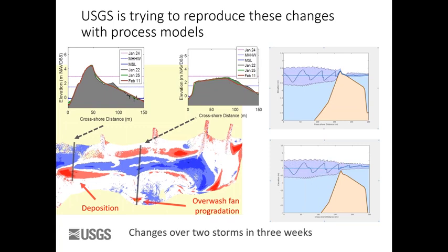This is SWASH. So SWASH is a Boussinesque-like wave-by-wave modeling system, and it's got multiple depths. I think there are 15 water depths in here, but it models individual waves. And I can talk more about SWASH to somebody, but this is the same model setup, but with the water depth higher. So we can compare how much transport would happen as the tide changes and the water changes over the course of the storm. Does SWASH do the sediment transport as well?